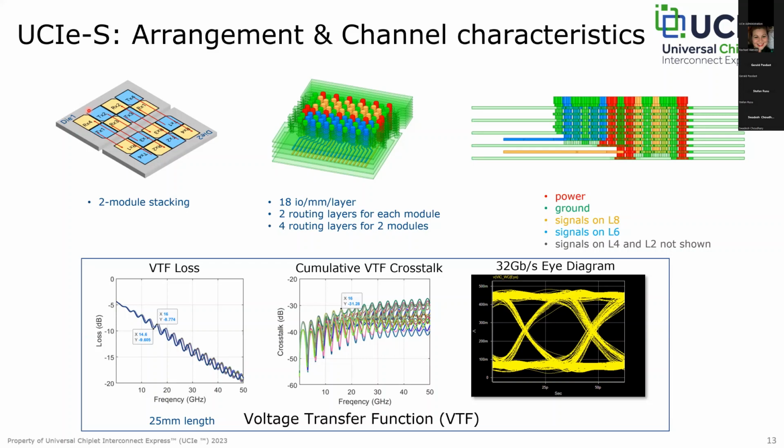You can see that the transmitter and receiver portions are placed in a checkerboard type pattern. And then here's the second x32, what the laser pointer is circling. And you have the same thing on die number 2, and the red arrows show the connections between the transmitter and receiver submodules. This checkerboard pattern is fairly important for interop and mechanical compatibility of die and how they're arranged. When you rotate a die, when you mirror a die, this checkerboard pattern becomes very, very convenient for making sure all the wiring is capable of being done.